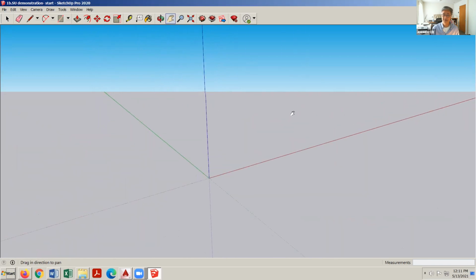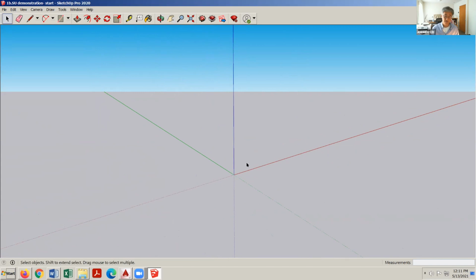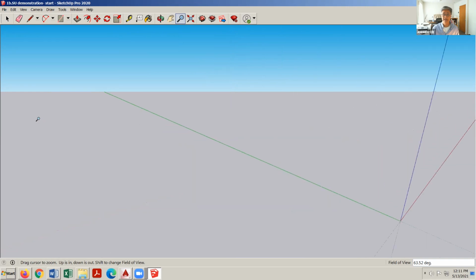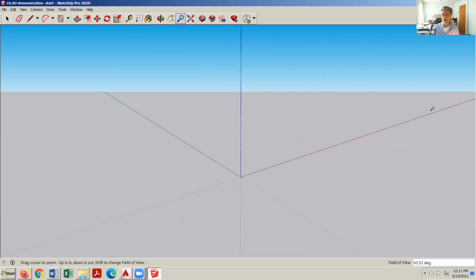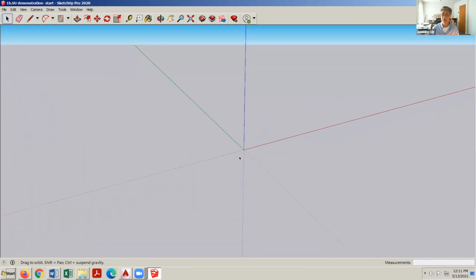and you can look around in your universe. And finally, the last way to move around in this world is zoom, which is, again, just like in AutoCAD, only in 3 dimensions. You can see the magnifying glass is zoom, and my shortcut is Z. I just type Z, and then I use my scroll wheel, and wherever you're pointing to with your cursor, that's where you zoom in. So if I want to look at the horizon over at this red axis, I point there and I zoom in towards that area. Okay.